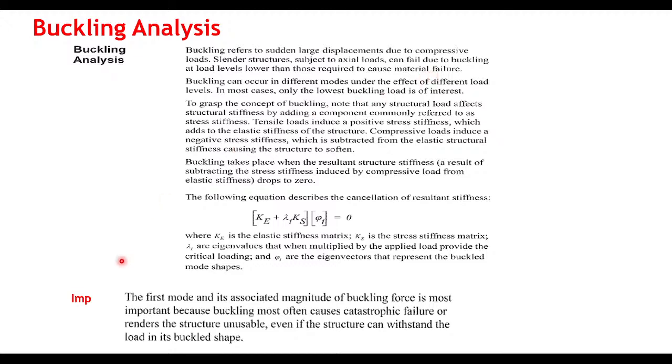Remember, while doing buckling analysis we try to extract the mode shapes. In short, we run a modal analysis, and we mostly consider the first mode as the critical load or critical mode shape if the component is going to fail. We can consider that mode shape as a reference, see the location where it is trying to buckle, and try to improve it. That is the best way to identify buckling. I hope this is clear.